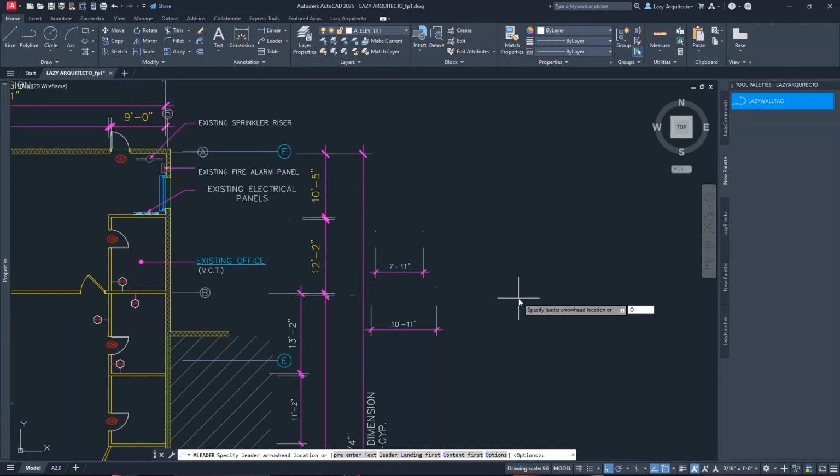When we create a macro, we try not to click or select options, but instead type the character. That way, if we are able to perform the command only with characters, we will also be able to add those characters to the macro code. So let's do that. Let's type O for options.